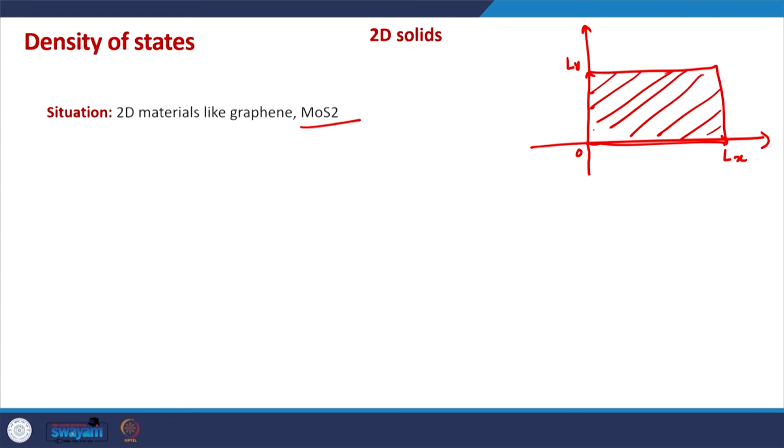By using the same principles and the same approximations as we used in 3D materials, if we have this kind of E-k relationship, where E is directly proportional to k square, or a function of k minus a constant square, a parabolic relationship between E and k, in that case we can precisely define the effective mass as constant.